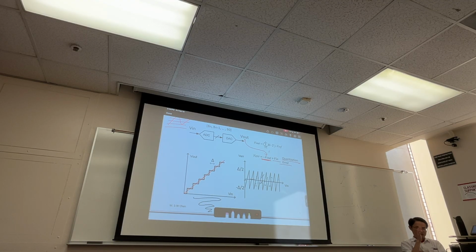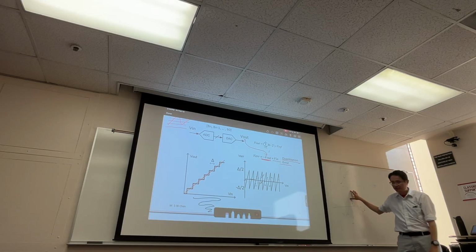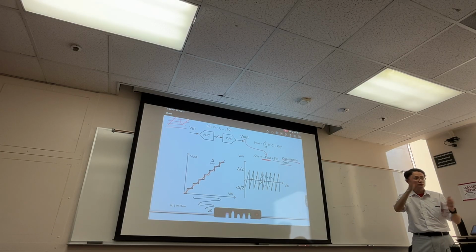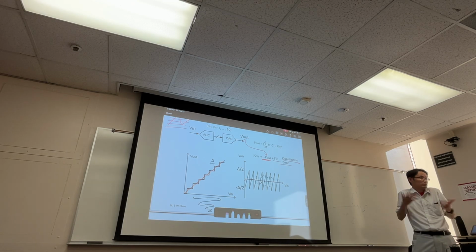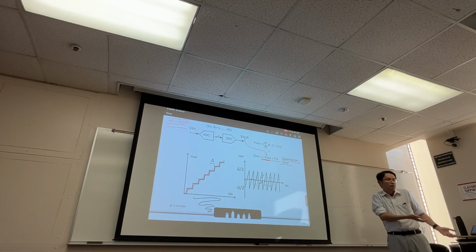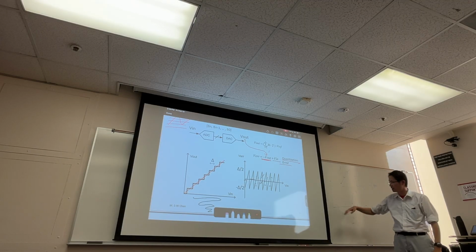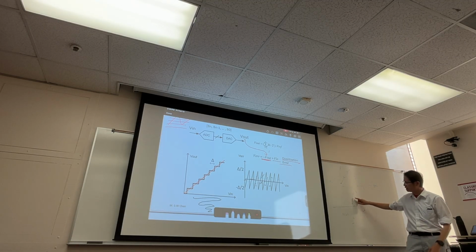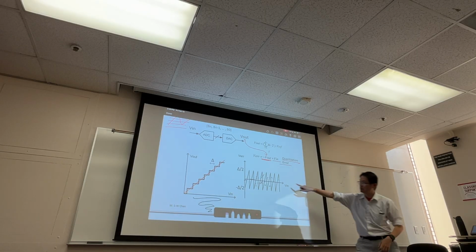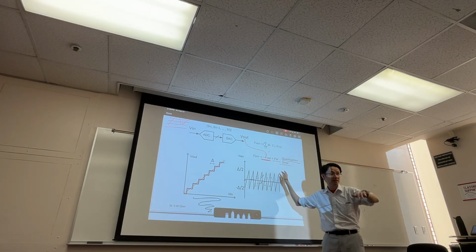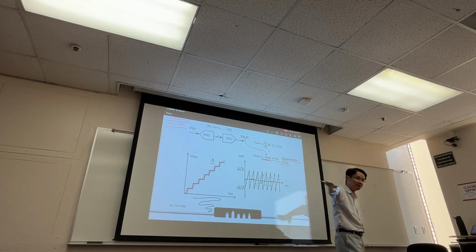Tricky, huh? Yeah, I know it's Friday afternoon and it's hard. So it really depends on the input waveform, right? If the input is somewhat random, it can be anything, like your Wi-Fi signal, or your 5G cell phone. Who knows what your friends are going to call you from or talk about? So all those are random. All these sample values are really random, with no correlation to each other. So of course the V errors are uncorrelated. That's why you see it's almost like a white noise.